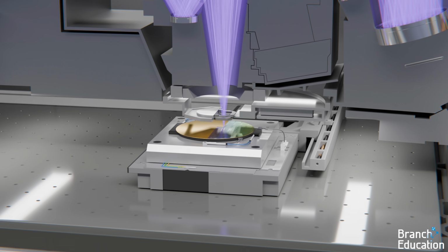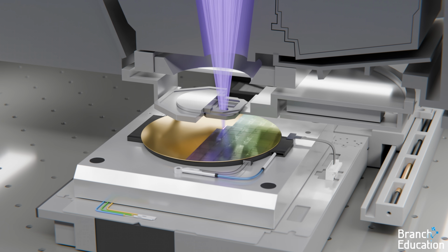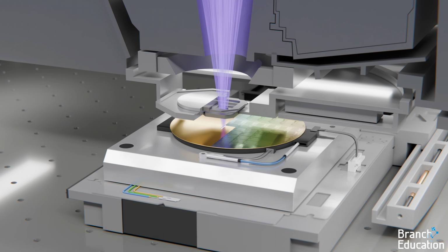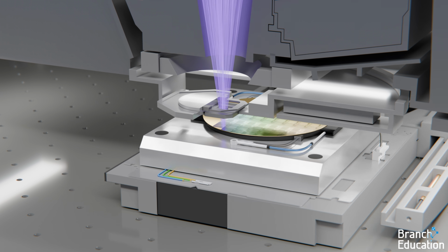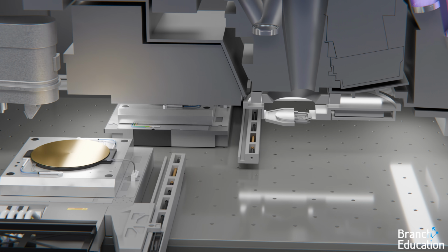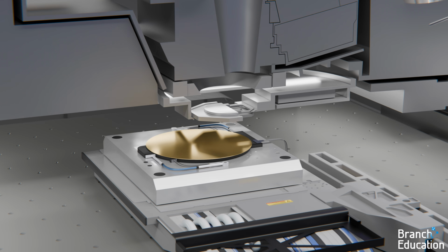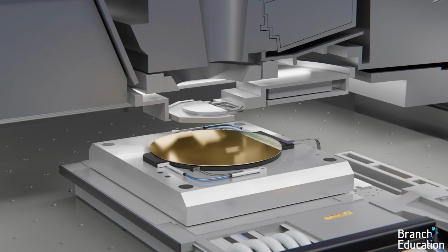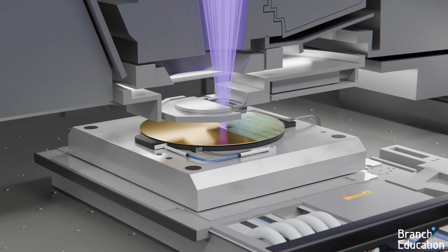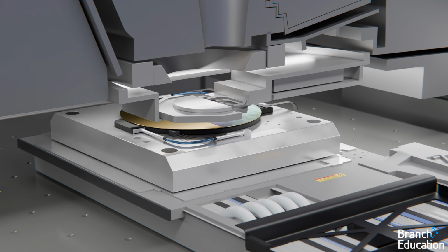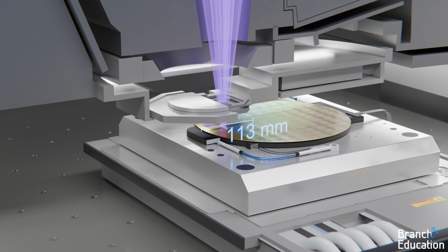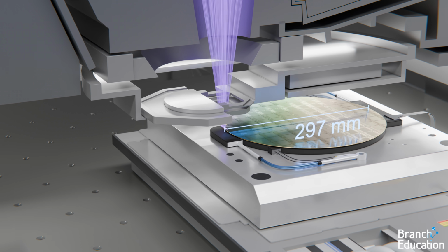The wafer moves to the next position, and the microchip design is copied yet again. This copying happens over and over until the wafer is filled with 100 or more microchips, and then a new wafer comes in and the copying starts over. This is the real-time speed of the lithography machine, taking about 18 seconds to duplicate the same microchip design around 100 times across the entire area of a 300mm wafer.